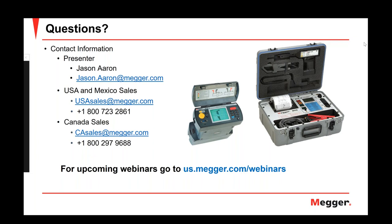The information that you get is going to look very similar to what we looked at whenever we went over the PowerDB form. You're going to have the tables for your impedance values and your cell voltages. You're going to have another table for your strap resistances. There's going to be some other information that we didn't really talk about in our presentation, like a table for temperature and a table for specific gravity in there. We just didn't have time in the scope of our presentation to go over that. So to answer your question, yes, you can use the Megger BITE 2P with PowerDB.